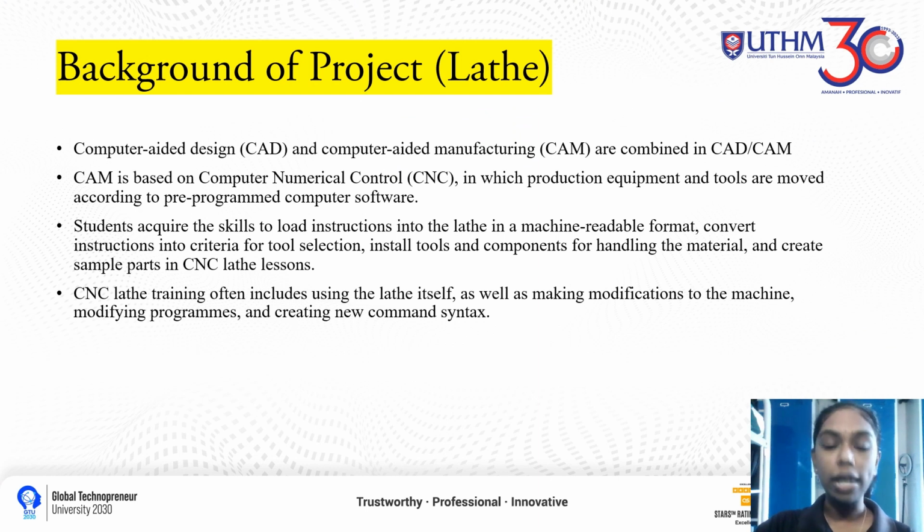Now I am going to explain about the background of project for lathe machine. Computer-aided design (CAD) and computer-aided manufacturing (CAM) are combined in CAD/CAM. CAM is based on computer numerical control (CNC), in which production equipment and tools are moved according to pre-programmed computer software. Students will get the skills to load instructions into the lathe in a machine-readable format, convert instructions into criteria for tool selection, install tools and components for handling the material, and create sample parts in CNC lathe lessons.